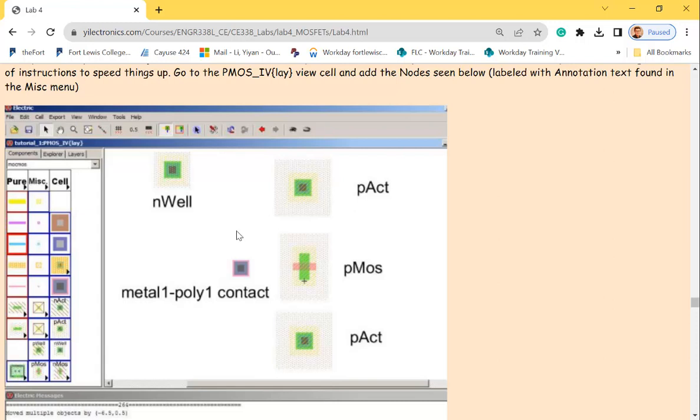See the little background, the dots. And the PMOS must be fabricated in N well, because N well is the body of the PMOS. So the N well is just N plus material. You don't see the dots. They are N plus material.